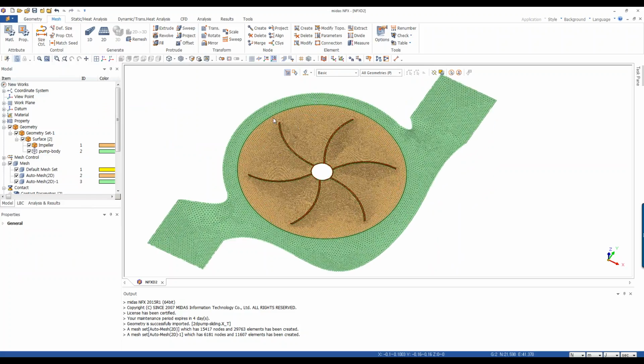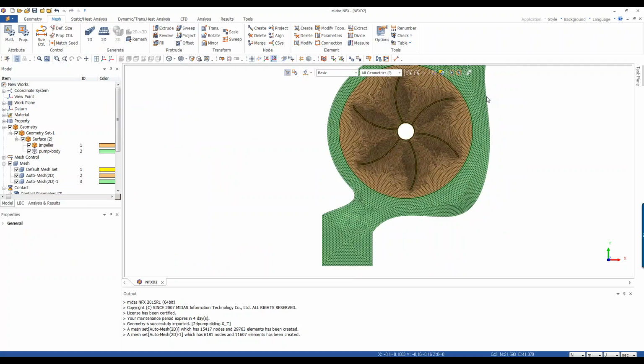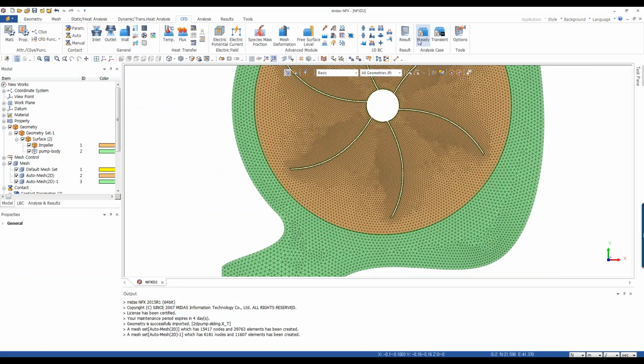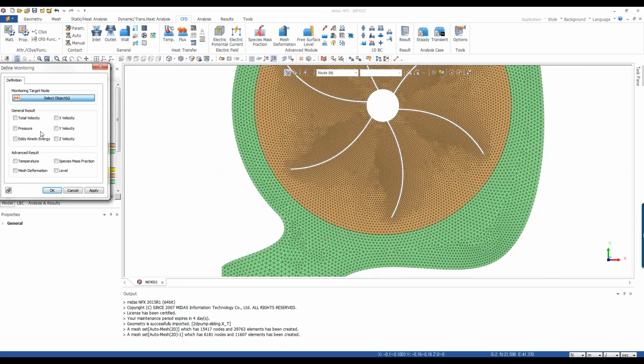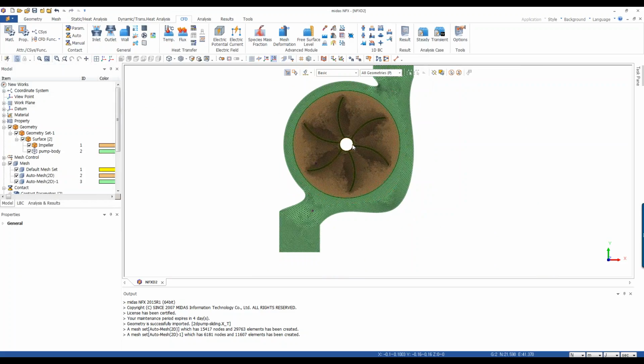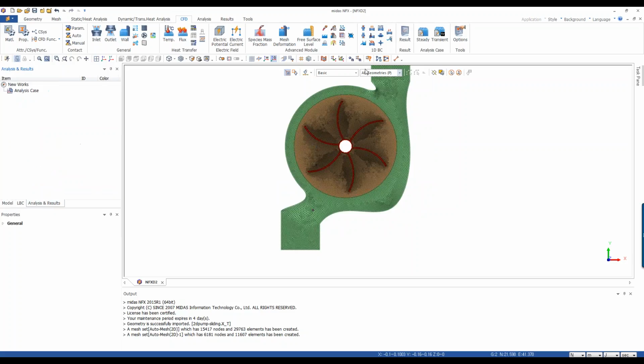Another additional thing that I'll do is that I want to know what will be the calculation of the velocity and the pressure during the analysis. So I will define a monitor condition. So I go here in the result for the total pressure at certain position. So I can select a node. So let's select 2 nodes like that. Click on OK, and it will monitor the pressure and velocity at this point during the analysis. So very useful function. So now that I did all that, my model is ready.